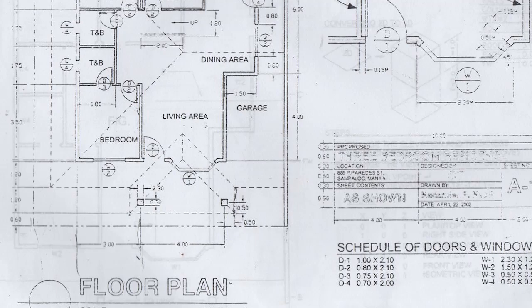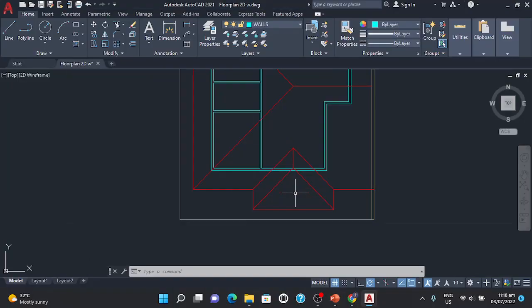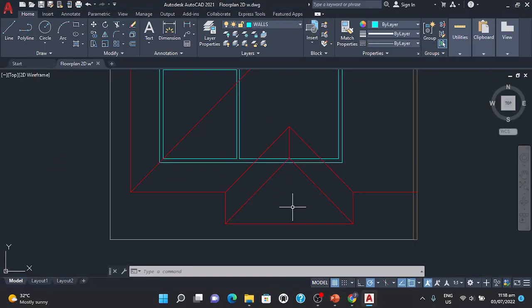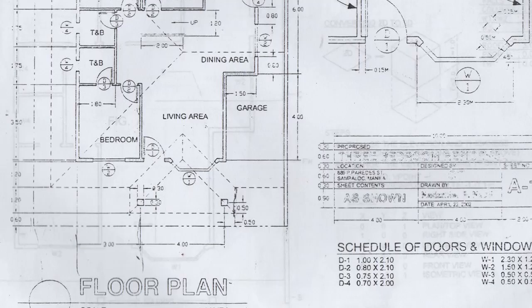Okay, so let's offset this specific roof line by 0.5 based on this drawing. Okay, so we will also create an offset of 4, or distance of 4, to create this right square. Okay, so let's go back to our drawing. So for this one, we have here the roof itself. So based on the drawing, we must offset the lower roof, or this line, by 0.5, to get the midpoint of this square.